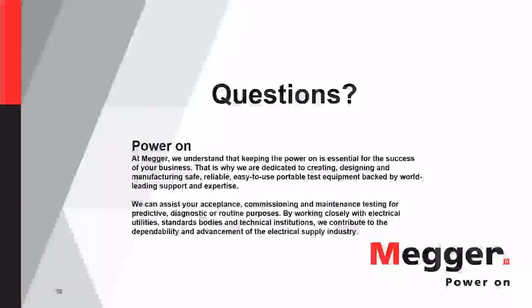I'll say that's kind of the way we name those, which is not the best. Really what they should be called is a gang operated and an IPO. So generally if you have 245 kV circuit breakers and below, they usually have one operating mechanism that operates all 3 phases. So you really want to use one transducer per operating mechanism. So if it's a gang operated, you just want that single, we call it single phase, but really it should be called a gang operated kit.